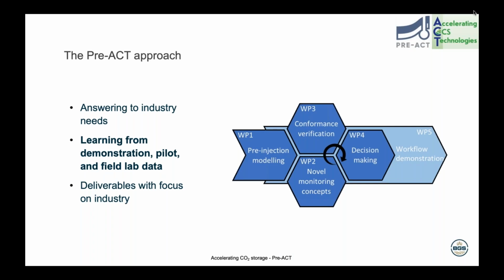So the approach of PreACT really can be summarized in the image that is shown here on the right. We've got a clear focus in the early work packages 1 and 2 on the modelling, the monitoring, and the understanding of pressure and saturation changes associated with CO2 injection. And then, taking the learnings that we make in these work packages from demonstration, pilot, and field lab data, and synthetic studies that we undertake, we feed these through into work package 3, where we're trying to equip operators and regulators with the tools to provide quantitative understanding of conformance.